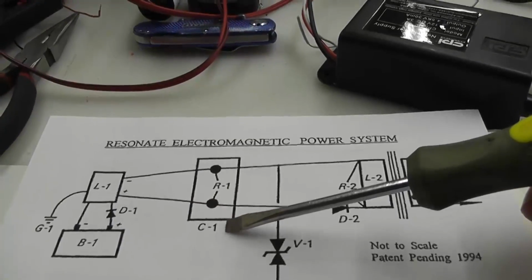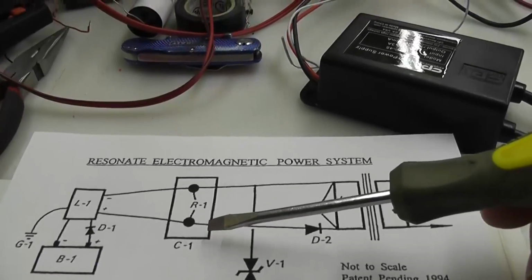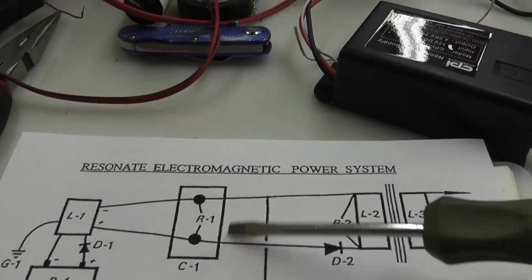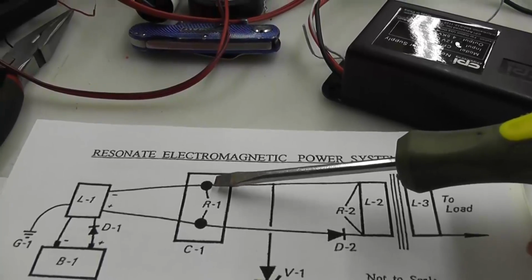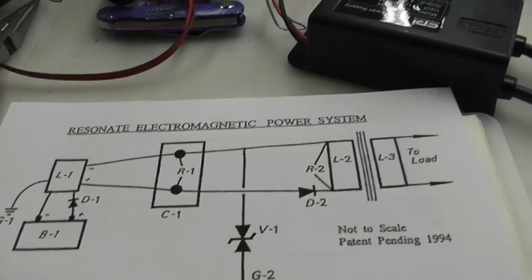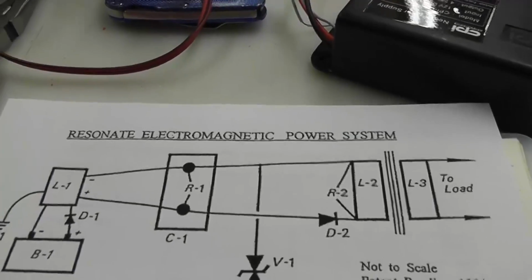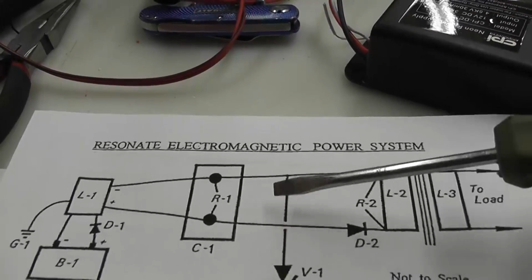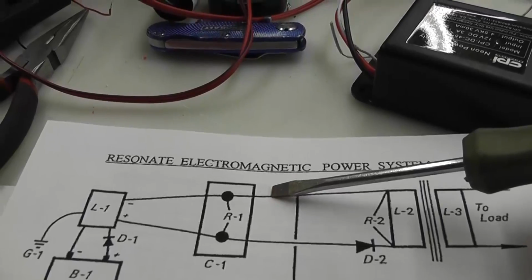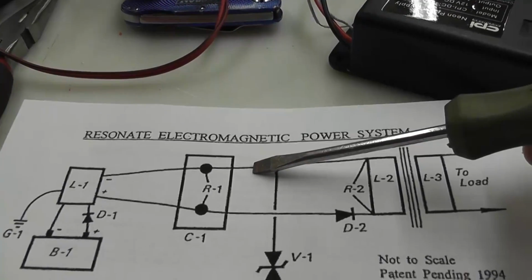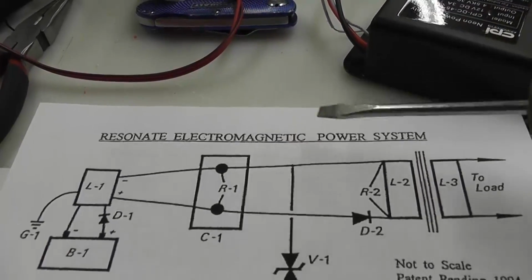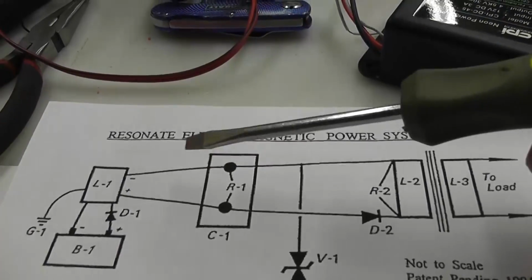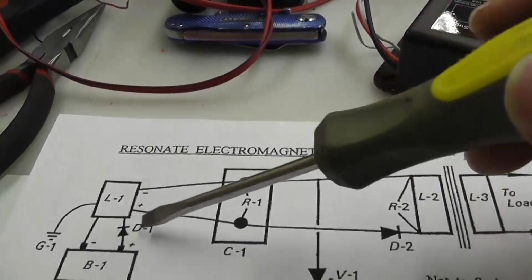So if you had one of the old school NSTs, which is like a giant brick, which is literally 2 coils, your standard step-up transformer, then it won't shut off. However, you will short it out and you'll burn it open. And if you put the proper capacitor in there, let's say, to find the resonance at 60 Hertz, because that's all they're going to put out, then you have an open there, and it changes the scenario, that you may be able to draw something off of this. So either Don had one of those old style NSTs, I had one, but I burned it open and I threw it away. If he was using one of those, then this changes some things, so not a lot. But then, of course, he's going to have an inverter in here too.